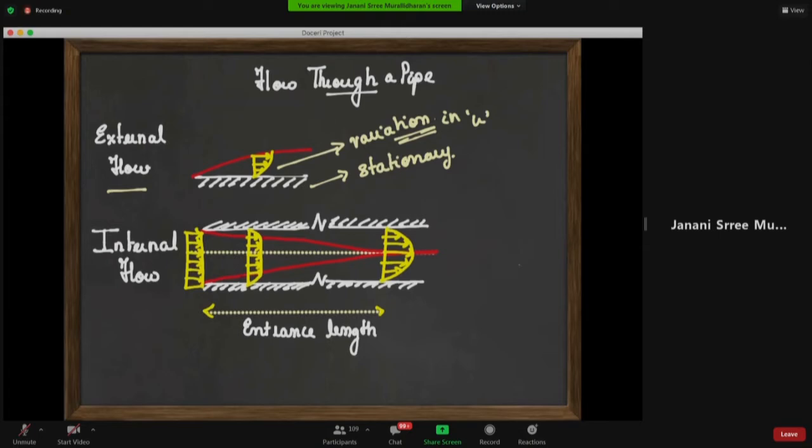So in an external flow, there is no other boundary which is affecting the formation of one boundary layer. Now, when you talk about internal flows, then you see an enclosed flow wherein the boundaries of this enclosure, in a way, modify and affect your boundary layer development.